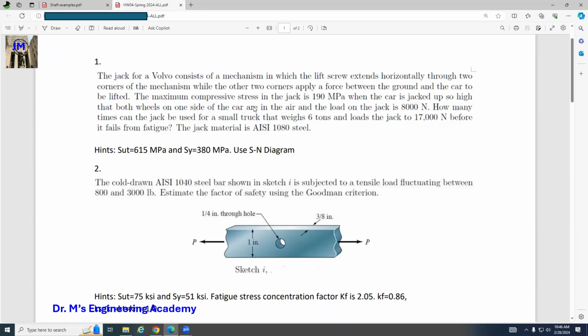Then based on equation 11.72, the IM. What is IM? IM is mass moment of inertia. Last time I told you, mass moment of inertia is not only related to the geometry, but also related to the mass. Mass means the density. So this equals KE, the kinetic energy we just got, divided by Cf, the coefficient of fluctuation of your torque, multiplied by omega average squared.